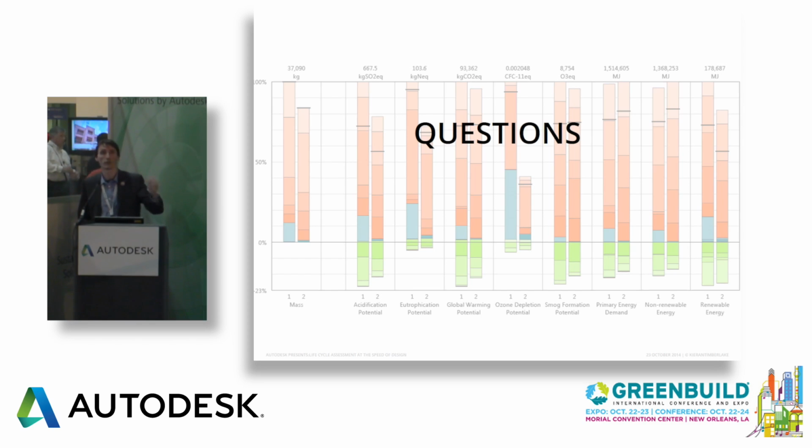One can certainly take advantage of BIM software nonetheless to generate schedules to feed to a cost estimator. But I think what you'll find is that the level of resolution and material detail that you need to conduct an LCA is significantly higher than what you would need to conduct cost modeling. So those complex wall assemblies for which we need to account for the brick, the sheathing, all those materials, I think a cost estimator would typically look at that assembly as a whole and cost that. So I think that would be one thing that we need to navigate, the different degrees of resolution.